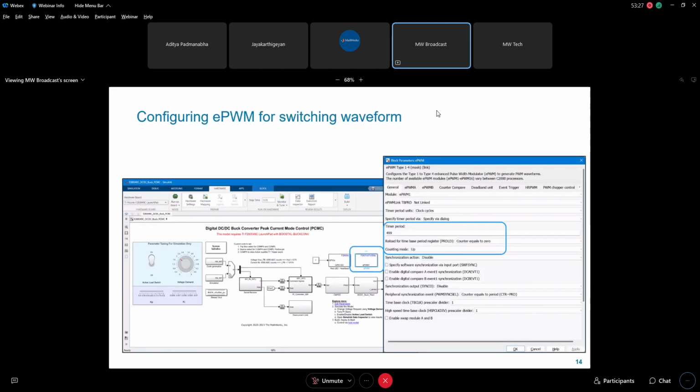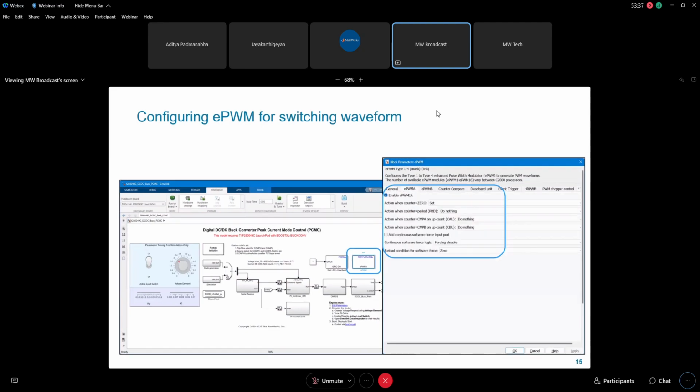First, we configure the counting mode as up and configure the PWM period as 499 clock cycles to generate a 200 kHz PWM waveform. For the EPWM action qualifier, we set actions needed to generate the EPWM waveform. Here, we are setting the waveform high by setting action when counter is equal to 0 and doing nothing for any other action events to achieve 100% duty cycle. To configure the action qualifier using trip 5 for proper duty cycle, we are making use of custom code.